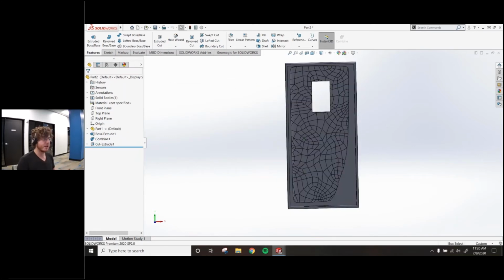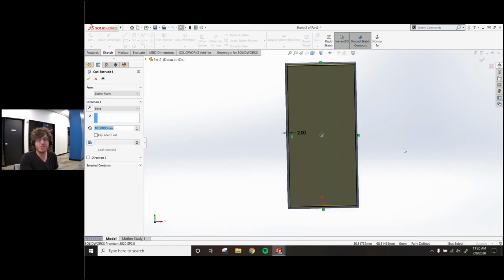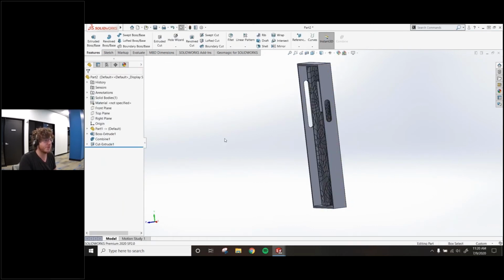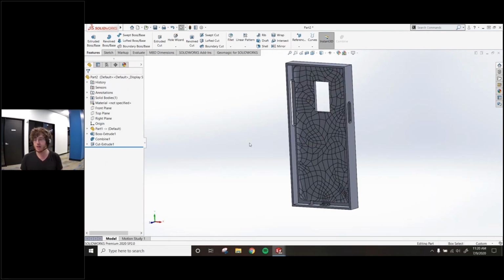It's because it's referencing that reference body. The phone is essentially the master model to this sub part. So we can really have a lot of editing features to that. And again, just being able to take a scan and bring it into Solidworks, and then doing that one-to-one conversion so I have something to work with, goes a long way. Instead of having to create a bunch of spline lines and maybe having to make this phone exact or another kind of part exact, just being able to do that conversion really helps out.